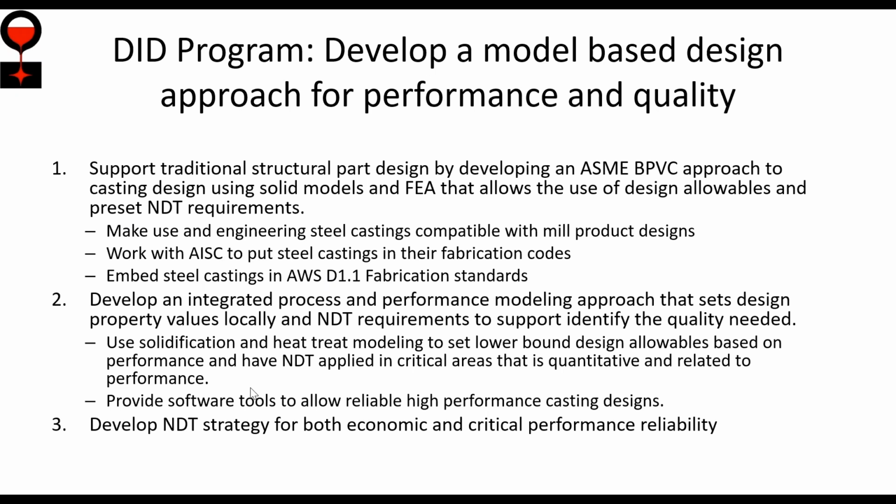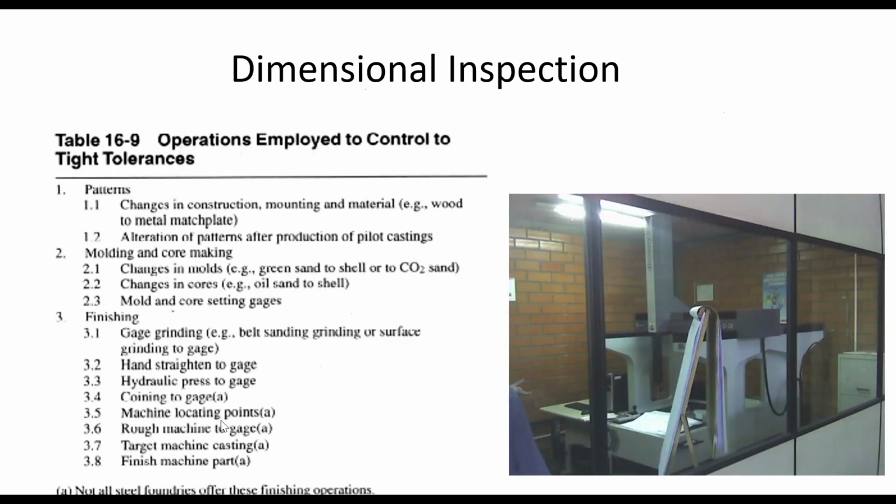that you're used to. Then for high performance equipment, we want to be able to use solidification modeling and identify what the properties are locally, but also identify those areas where I'm concerned about performance and I need some kind of quantitative NDT to assure critical performance reliability. And that means we need to develop some new NDT standards that allow us to do that.